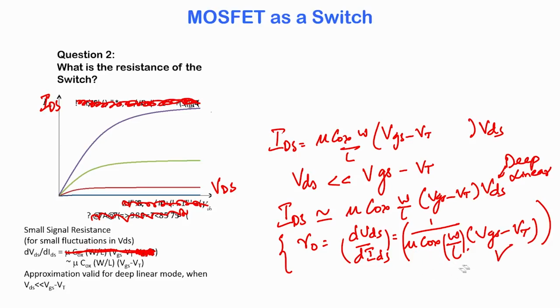But let us now go ahead and start defining each one of these terms. What is mobility? Because we are talking about the output resistance of the MOSFET. Now, what is the mobility? The mobility is connected to the mean collision time, it is q times tau collision by the effective mass of the carrier.